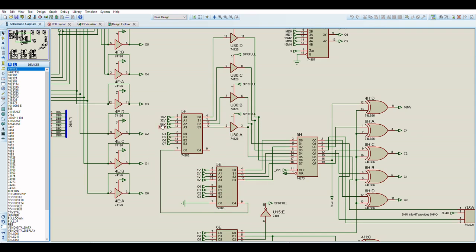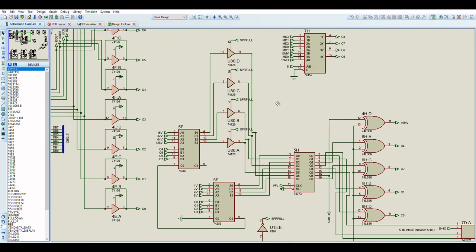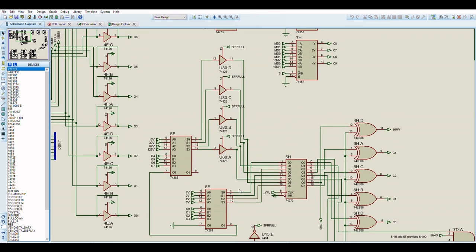Now the sprite position, when it's stored in its sprite register memory, is actually, if I remember correctly, inverted. So instead of doing an 8-bit add, it's actually doing a subtract. And what it's doing is that the lower 4 bits just get clocked straight away and get stored straight away into this latch here on the comparison.